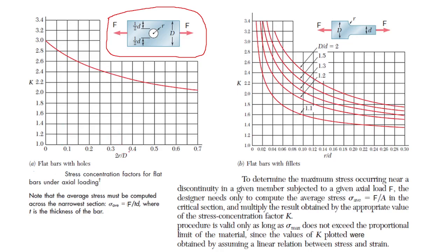If we know the geometry and size of the slab and that it is drilled, we can find this ratio. Then from the graph, for instance, if the ratio is 0.45, we reach this point, which corresponds to a K factor of 2.2.